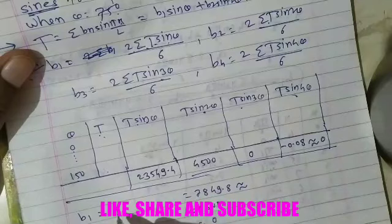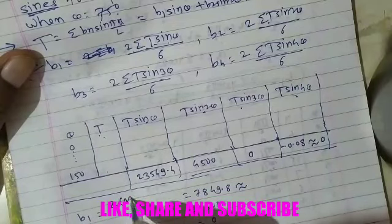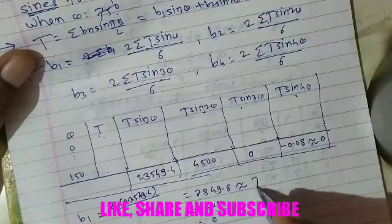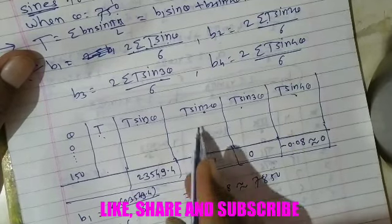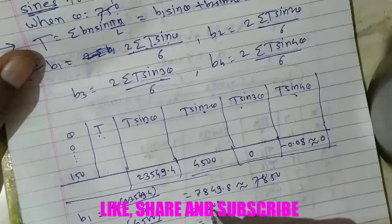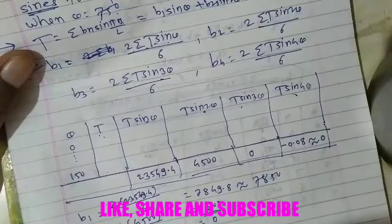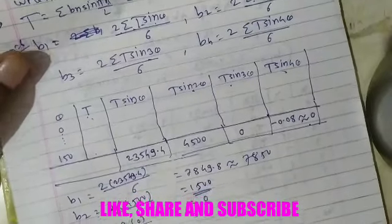And after getting the summations, write b1. So b1 is 2 times the summation of t sin theta, that is 23549.4 upon 6. Calculating this, we get approximately 7850. Okay, b2 is 2 times the summation of t sin 2 theta, which is 4500 upon 6. After calculation this is 1500. And b3 is 2 times the summation of t sin 3 theta, which is 0, upon 6, that is 0, and similarly b4 is 0 because the approximate value is 0. So b3 and b4 are 0 here.